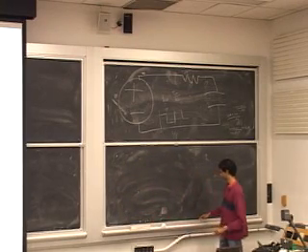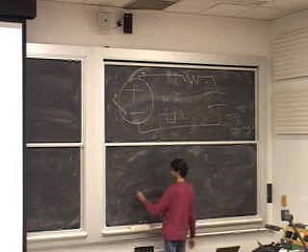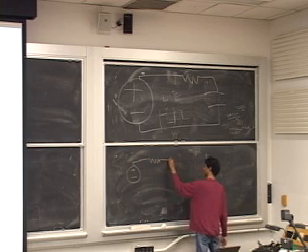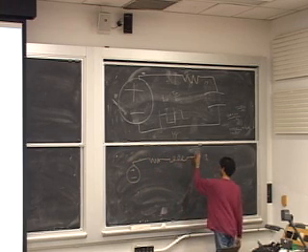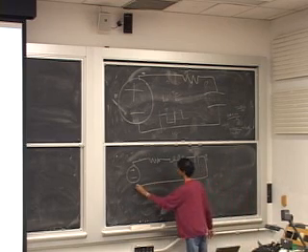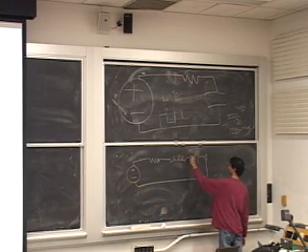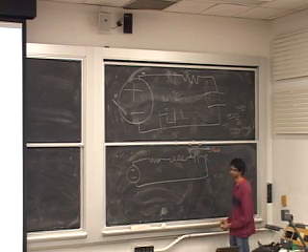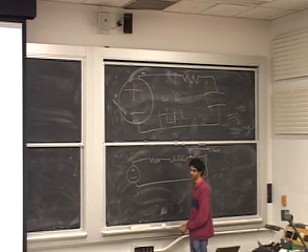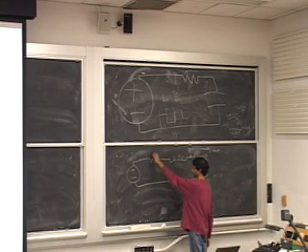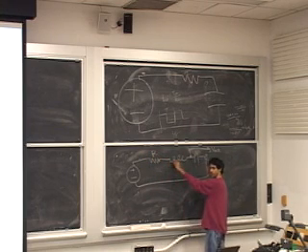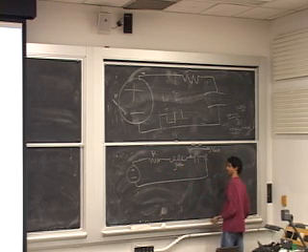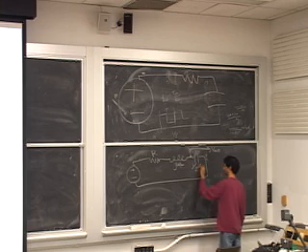So now we can get to things that are a little more interesting. Let's say I had a voltage source. I have a resistor, an inductor, and a capacitor. They all walk into a bar and say, what's the output voltage across the capacitor? Okay. So first, we would start by finding out what's the impedance of the resistor. It's R. What about for an inductor? j omega L. And for a capacitor, it's 1 over j omega C.